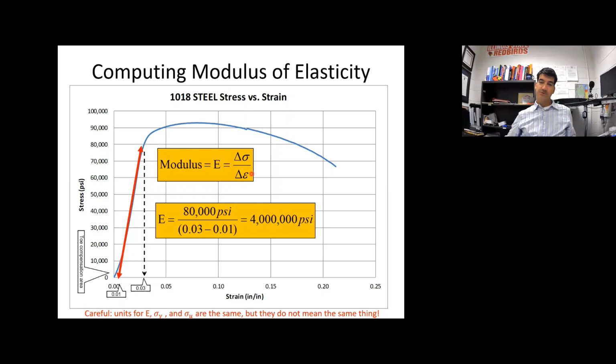However, for the purpose of stating the elastic modulus, this is just a convention. I don't know how this started, but the convention is to say that in the denominator, the inches per inch, they cancel out. And so your units for elastic modulus are simply PSI, right? That's the way you'll always see it. If you go on matweb.com or look up in any materials textbook, the units for elastic modulus are always in some unit of stress, whether it's PSI or KSI or pascals or megapascals. It's going to be some unit like that. So for our purposes, you'll put them in PSI.